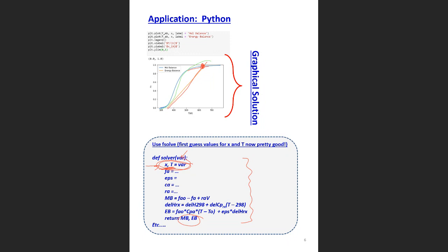Right? But what you must realize, when we solve these mole balances, so let's just write the two balances, FA minus FA naught plus RA times V, and here I've got my energy balance, I don't have to rewrite. Here I've got it there. I actually have much more than just those two unknowns there. Many more. I've got FA, I've got RA, the volume was specified in this case, and in RA I've got CA, that's a variable, and in my RA equation I've got K, so I actually have gazillions of variables, and if I want to, I can for each one write an equation.